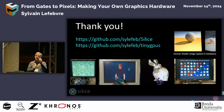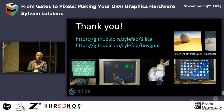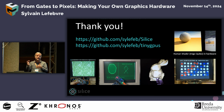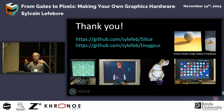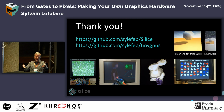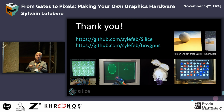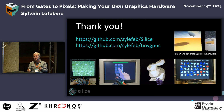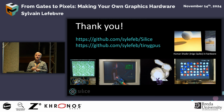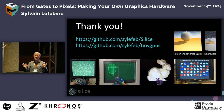It's actually not very difficult to reuse pieces of hardware and plug them together if you have planned for it initially. There are even standard buses like AXI, where people have agreed on ways to communicate between the different peripherals. So you can assemble your hardware and then get it implemented. Typically on FPGAs, this is great because it's just milliseconds, right? And in the automotive industry, for instance, like in many other industries, FPGAs are very popular. The big advantage being that even if you made a mistake in your hardware, you can fix it, right? With an ASIC, not so much.